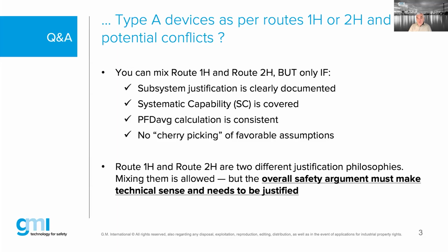It has to tell you what you have to do to achieve or to maintain during your proof test or during the duration of your mission time. What do you have to do in order to prove that this system is still reliable at the level of SIL you're trying to use it for? Systematic capability. Besides the SIL number, SIL is not saying anything about the quality of design. The systematic capability will reflect the process of the design or the rigorousness of design.